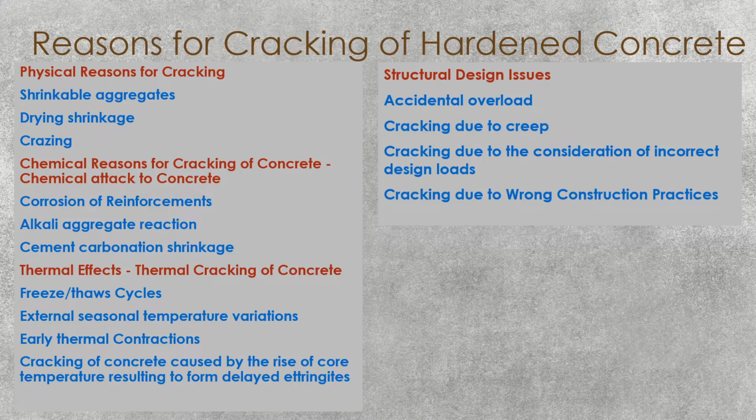Now, if we are unable to maintain the temperature at that respective level, there may be a chance of formation of delayed ettringite. Formation of delayed ettringite increases the internal volume of the concrete. With that, concrete could crack.